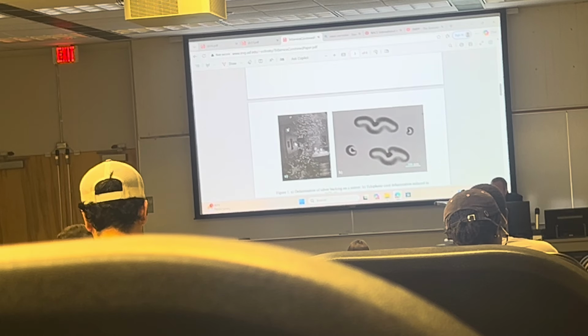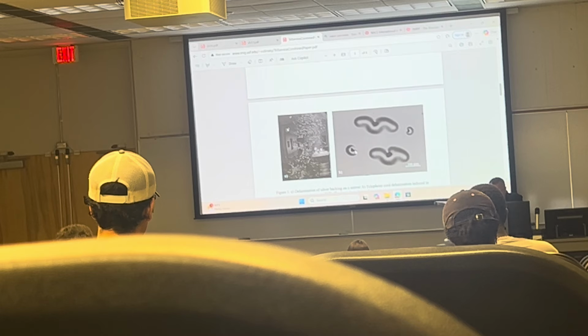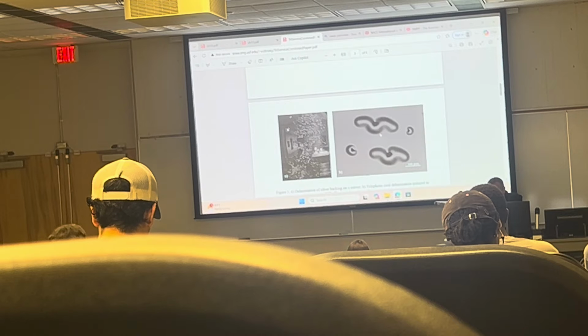And this is the deterioration of a mirror. And this is an old metal coating. These blisters are induced by an indent, you see? And the reason the delamination propagates is because there's residual stress that drives this delamination.